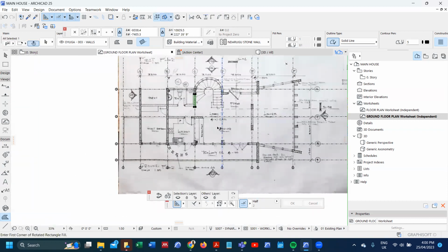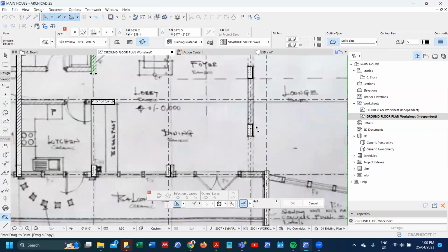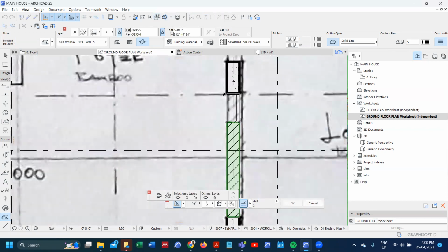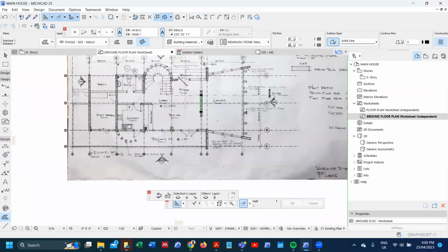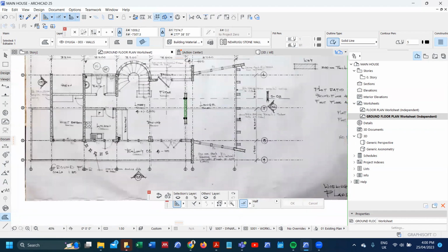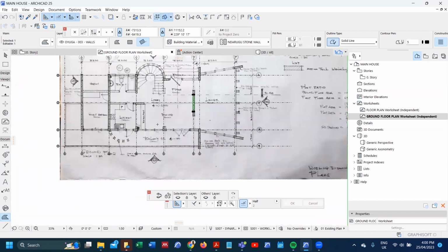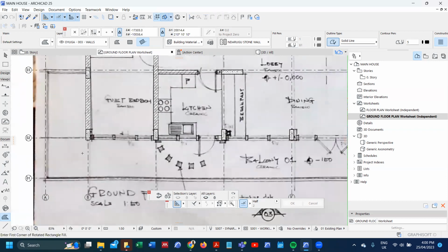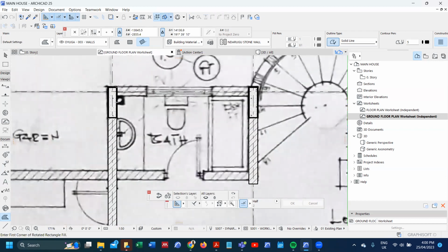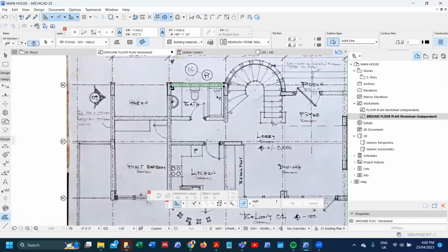I'm deliberately putting all the vertical looking walls. Any other vertical wall remaining? This is predominantly a window feature, so I can leave that one for now. Let's act on the horizontal walls. I always, again, like starting from a known point. That's the edge of a column. So if you put 200, place that one, you're good to go.